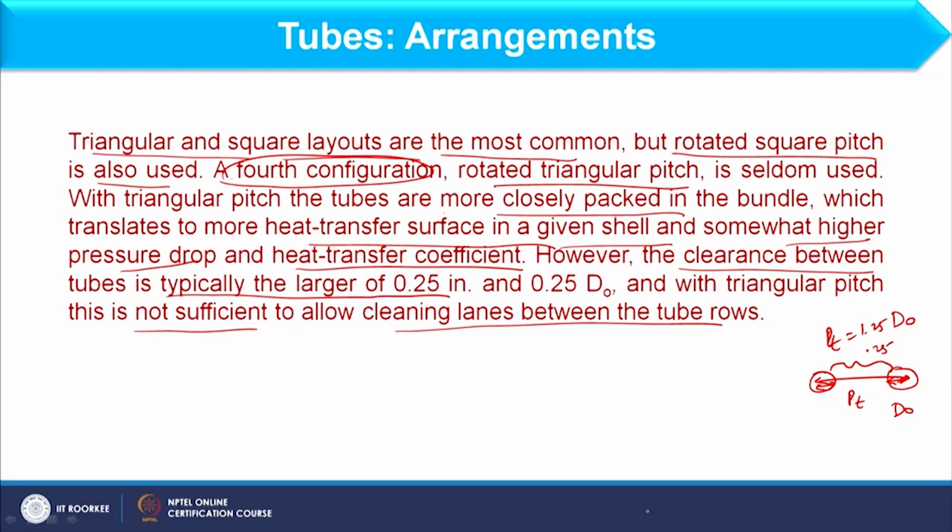Or in other words, what can we do? If cleaning is required, the formation of scale or whatever problem there is in the shell side will be because of less gap between the tubes in the shell side, right. So, that is the problem in the shell side, not in the tube side. So, how can I address that? I can provide a less fouling tendency fluid to the shell side.